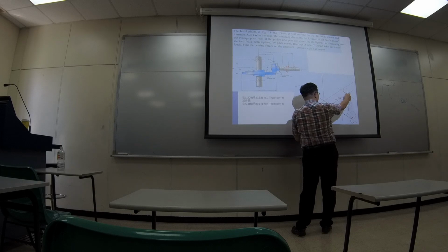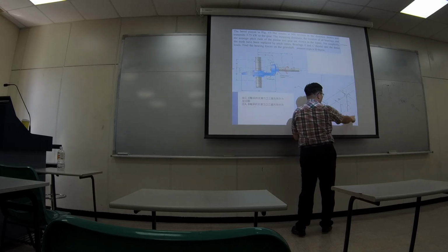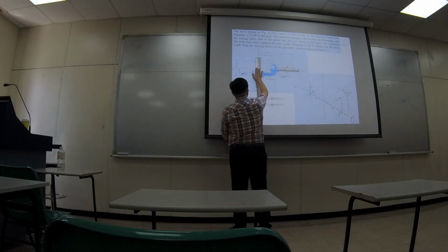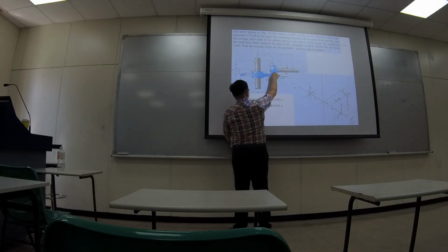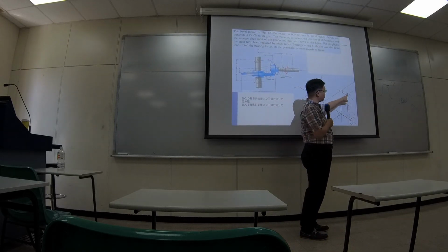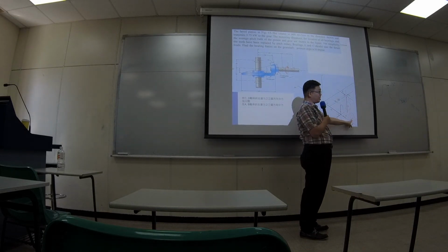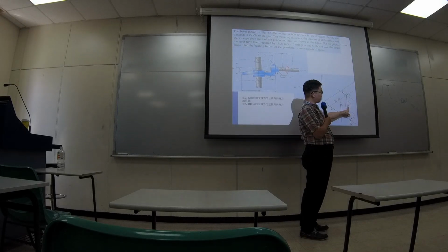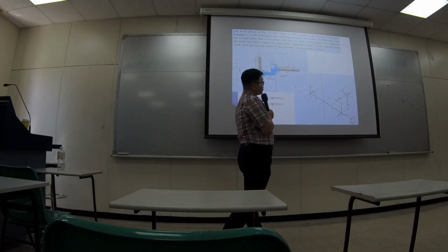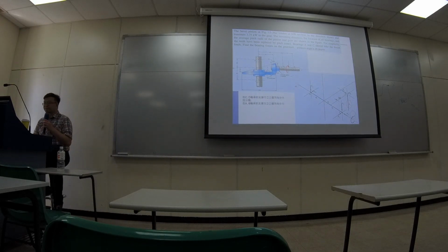you actually have some forces that are not exactly applied on the shaft itself. It's actually having a force applied somewhere outside. So for this shaft system, the force comes from here. Okay? So, for example, this WT is going to generate some kind of moment. So the torque right here is going to balance with the moment generated by WT, right? Then you can compute how much torque is generated right there. Okay? So that's pretty much what I want to talk about.